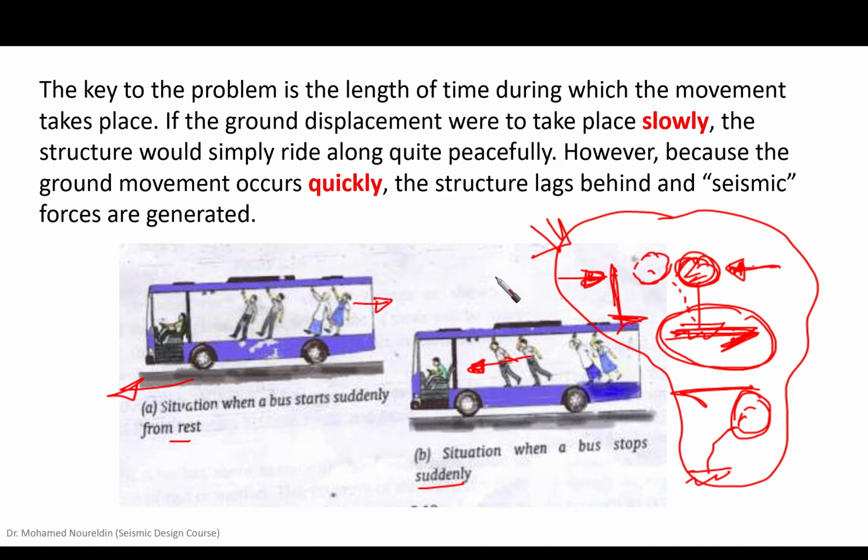Then what about the damping? What about the elastic forces? What about these kinds of issues? We are going to take into consideration all other forces using some factors, so that we take into consideration the system type, whether it is a moment frame, a braced frame, an ordinary moment frame, or a special moment frame, or whatever. The system itself is going to be reflected in some factors. And similarly, we are going to do the same for the deflection, for example.